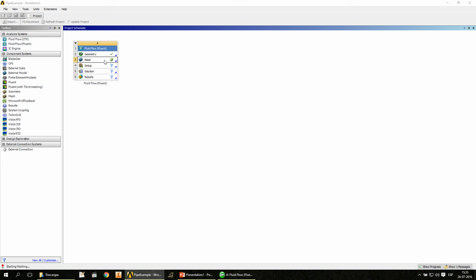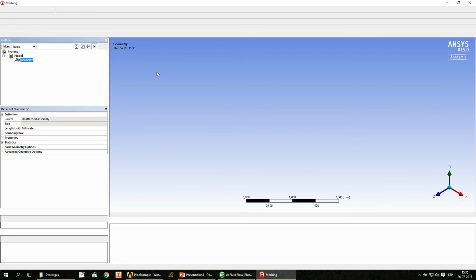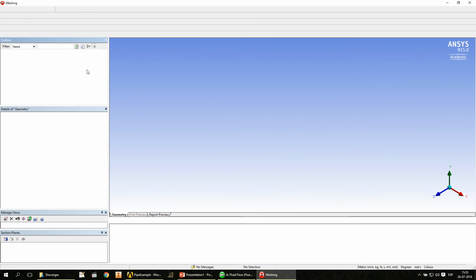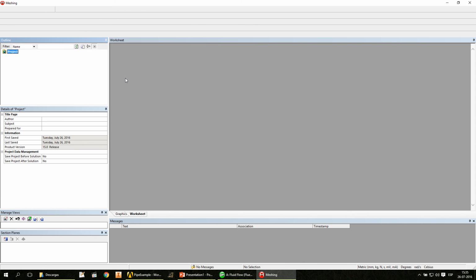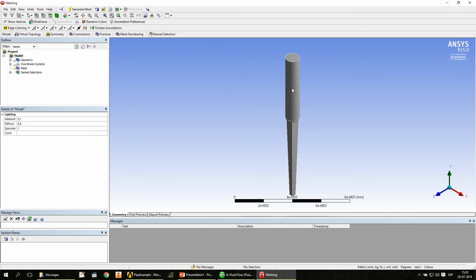For this step, it's crucial to have the inlet, the wall, and the outlet named on the geometry. And with those names, yes, you have to be very accurate. You can't name the surface as you want; you have to do it that way. Okay,